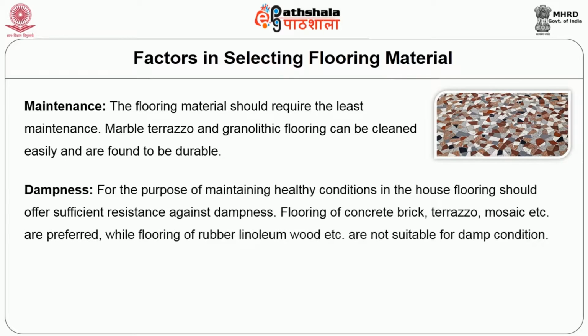The fifth one is dampness. For the purpose of maintaining healthy conditions in the house, flooring should offer sufficient resistance against dampness. So flooring of concrete, brick, terrazzo, mosaic, etc. are preferred, while flooring of rubber, linoleum, wood, etc. are not suitable for damp conditions.